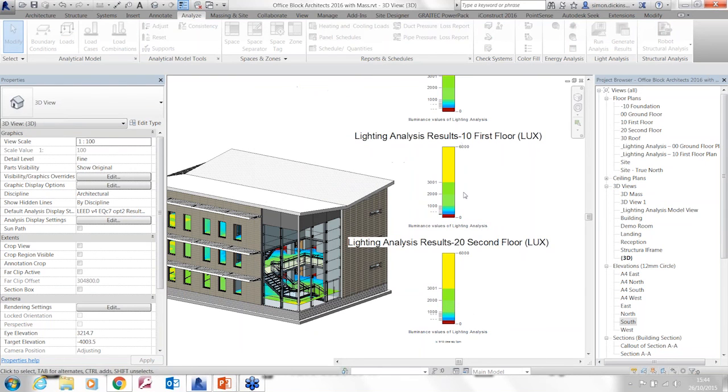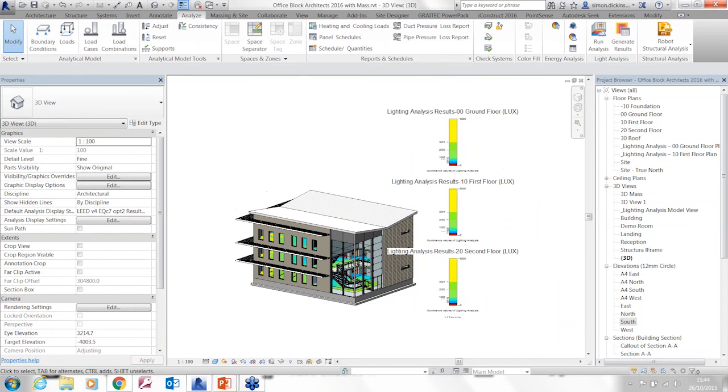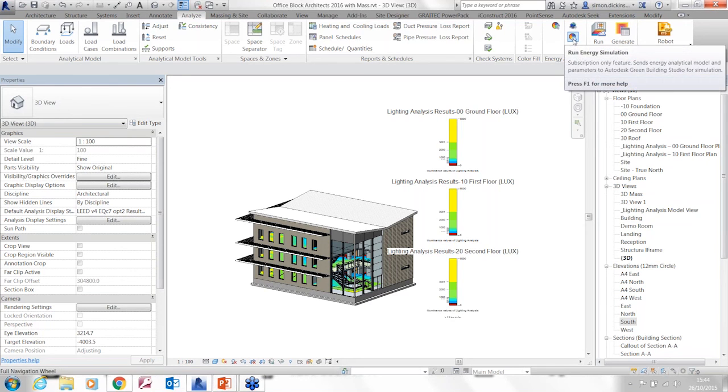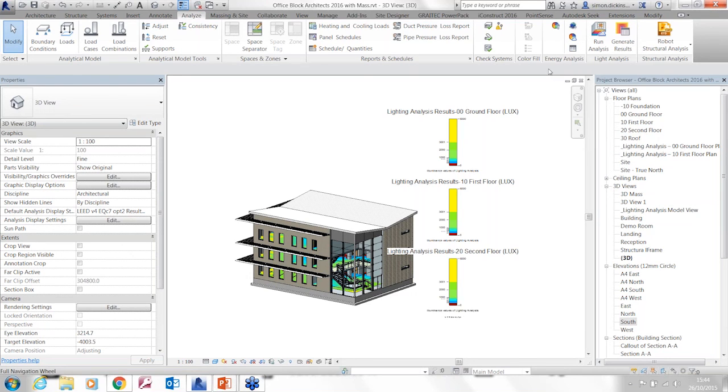So the tools that we've got are incredibly powerful. The majority of them, as long as you're on an active subscription, are pretty much free to use other than the cost of the subscription. So you can run as much energy analysis as you need on a particular building and analyze every different change, whether you're changing the thickness of a glass, taking it to triple glazing from single glazing, adding solar shading, or putting a more insulated building structure together. Is it timber frame? Is it a timber clad building? All of these can be taken into account by the energy package.